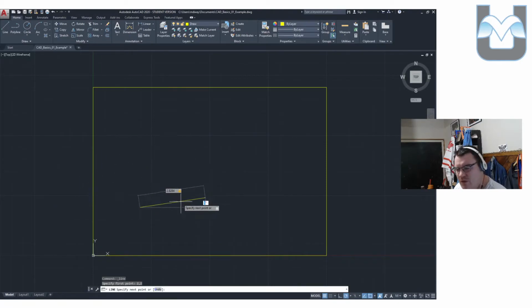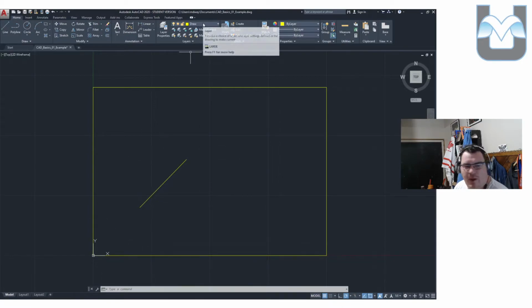So you could go from 0 to 180, and if you drag it in the negative direction, you can go 0 to 180 as well. In this case, the version of the drawing I'm making is 45. So I'm going to type that in, and we're going to have our line right here that we can start with. I'm going to dimension it right away because it makes sense to dimension some pieces of this.